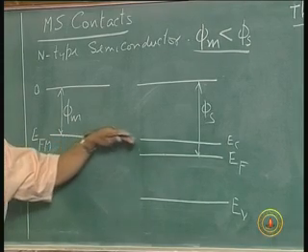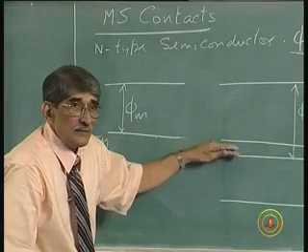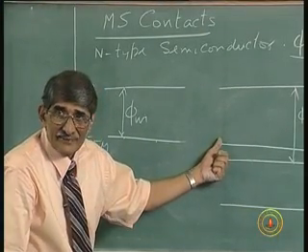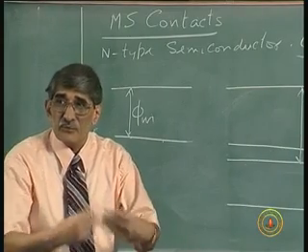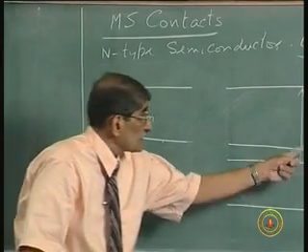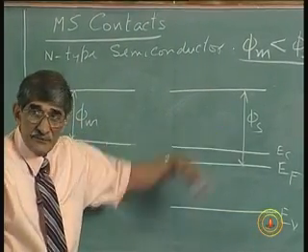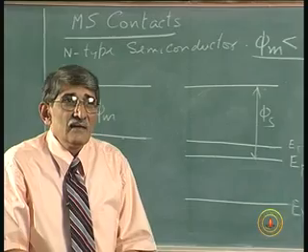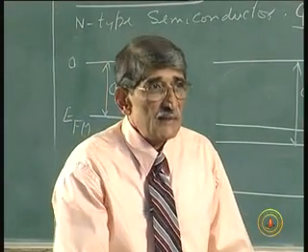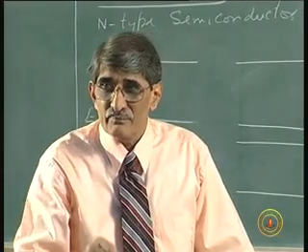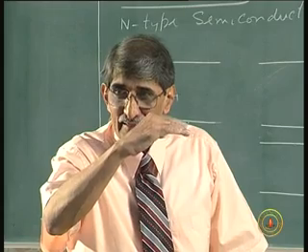The electron transfer from here to here means you are charging this portion negatively. Okay. It will become more n type near the surface, and if it becomes more n type, it becomes difficult to transport these electrons into that portion. So, the neutral portion here, the energy band diagrams here will actually go up. If it is negatively charged, when you take an electron near that, it gets repelled. That means you have to spend more energy to take the electrons to that point. So, once it is negatively charged, the band diagram will move up. Okay, that is the key thing to understand.